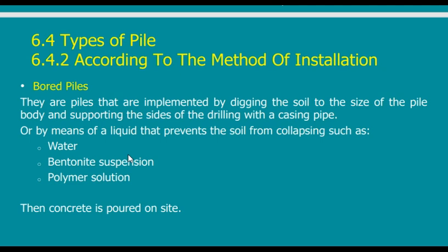So instead of having the side of the hole be sand, it will be covered with a silty material that will help the hole stay open for a longer time. So this is the bentonite suspension. There are other polymers that may be added to this material, and they would help.